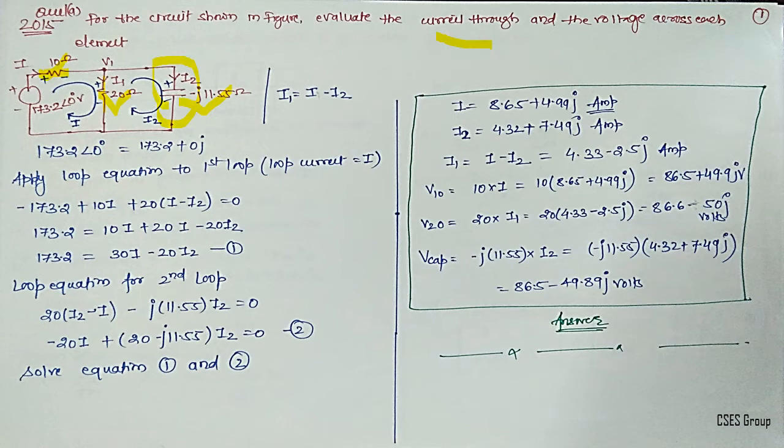This is a sinusoidal steady state problem. You need not bother about the initial condition here. Please remember, guys, whenever you have an SS problem, sinusoidal steady state, you need not bother about the initial condition. The initial condition is immaterial now, because your circuit has no initial condition. Please make a note of it. If that is the case, you just need to apply simple KVL and KCL, and you can easily get the answers.